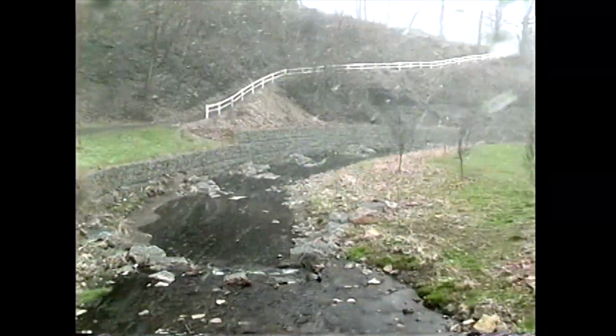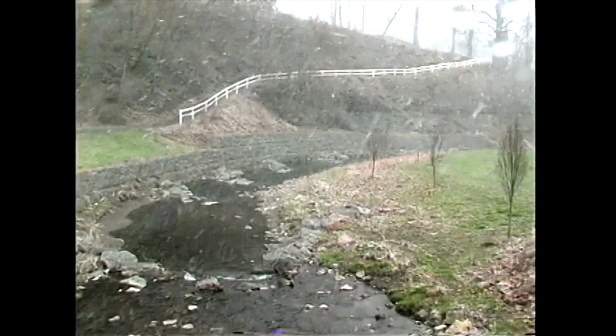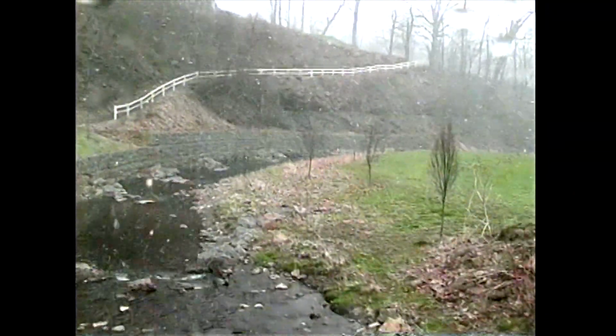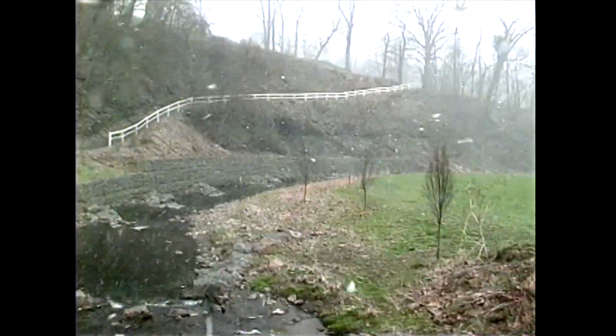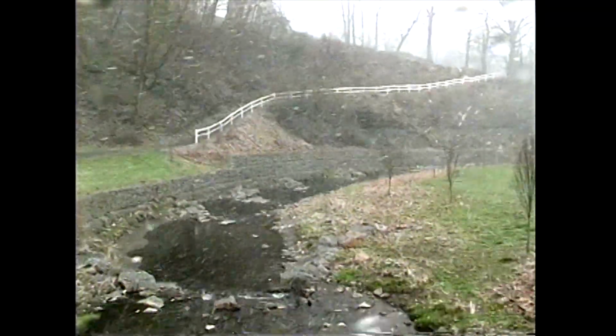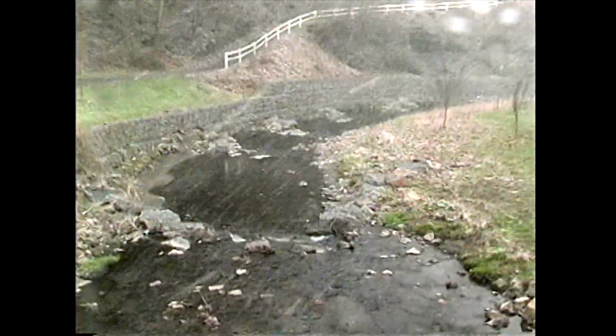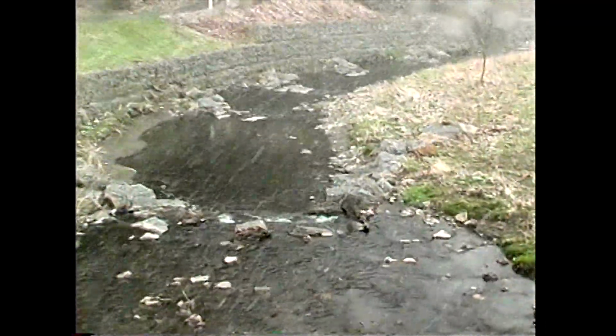Okay, here we are at the next portion of the project area, and this is right below the second tee, where you cross the bridge to go to the second hole green. The structure you're looking at in front of us is called a cross rock vane, and the part of the cross rock vane in the middle of the stream is a low point, and so gravity pulls water to that point throughout the year.